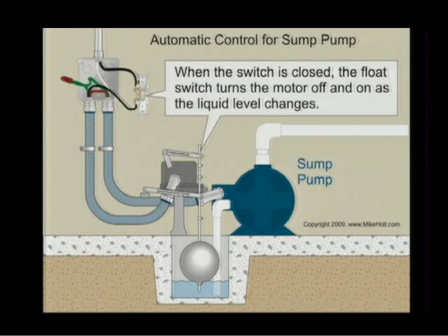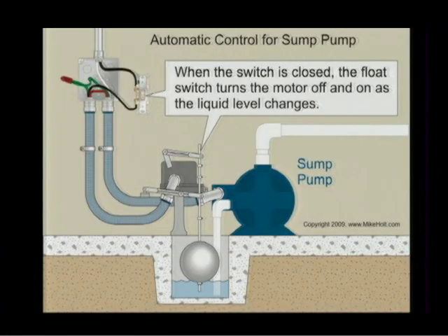Or we could use the normally closed contact and turn on a pilot light, or an alarm. You're saying I could add a flow switch here with a normally open contact, so that if it flows, then the green light comes on. And if it doesn't flow, then the normally closed contact would be closed, and the red light would be on. So I could tell whether or not there's any liquid moving just because I can see the lights. The red light would be on as long as that normally closed contact in the flow switch is closed. But the green light can only come on if the green light bulb is good, and if we're having flow, and if we have voltage.